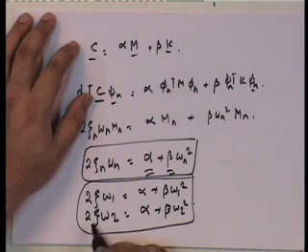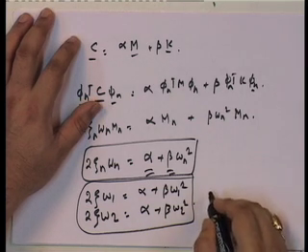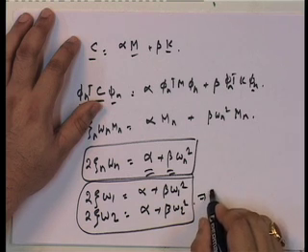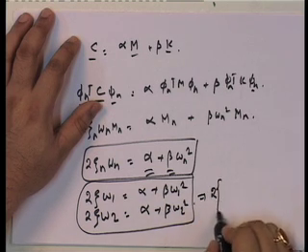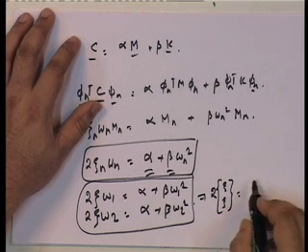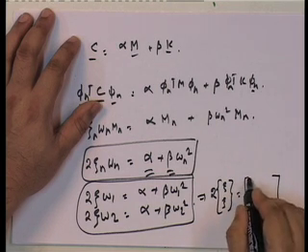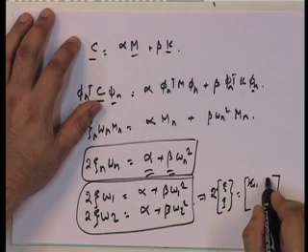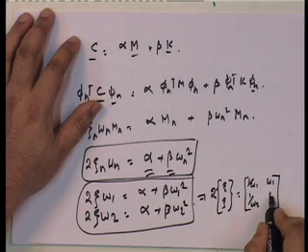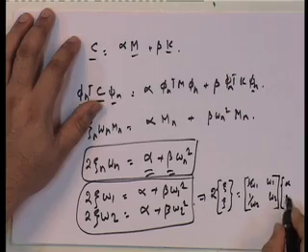I am going to take the 2 out. So, what do I get? I get the following: 2 xi times the vector of 1 and 1 is equal to the matrix with 1 upon omega 1, omega 1, 1 upon omega 2, omega 2, times alpha and beta.